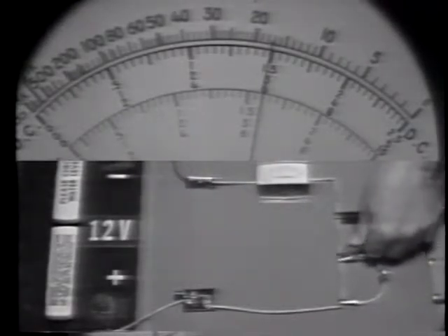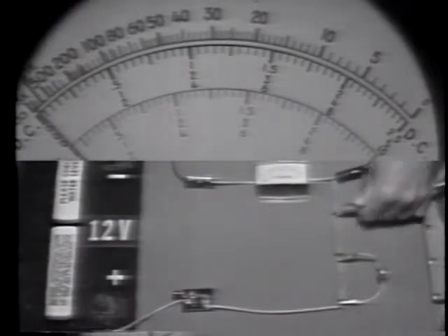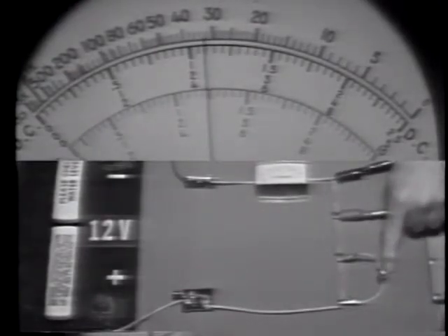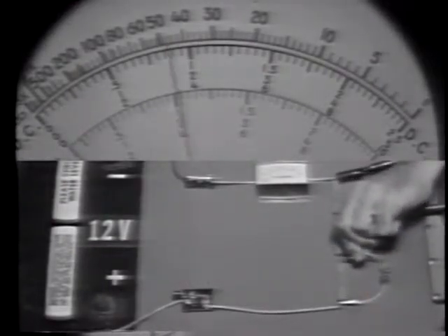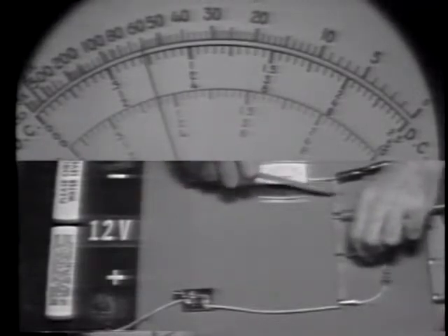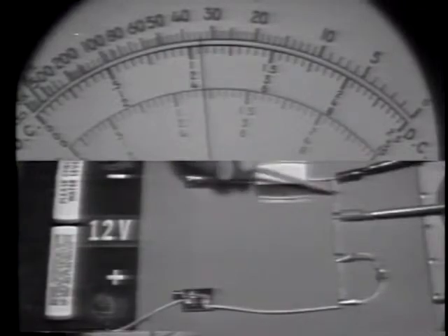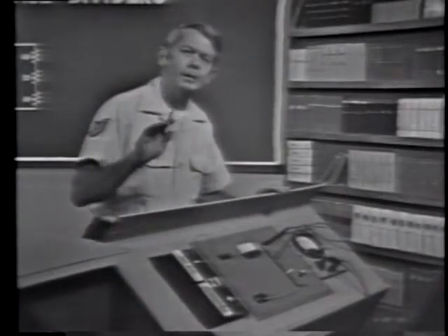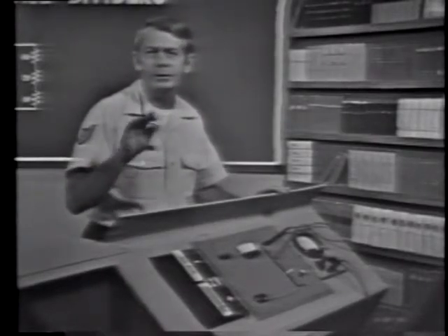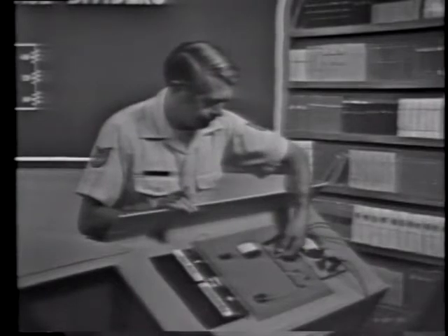Let's go up and check this one. Observing polarity as I make the connections. Okay, with the load device connected, the voltage here is a little over 4 volts. When I remove the load device, the voltage here decreases. When I load the circuit, the voltage here increases. Okay, loading the circuit changes the voltages in the divider. Let me remove everything and we'll figure out why.